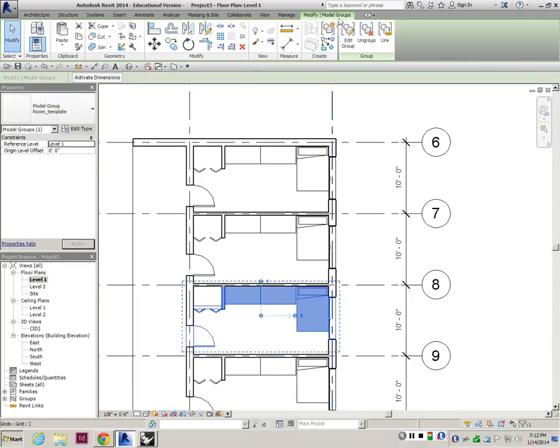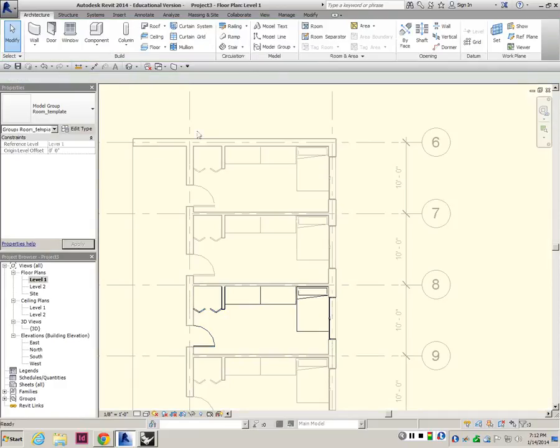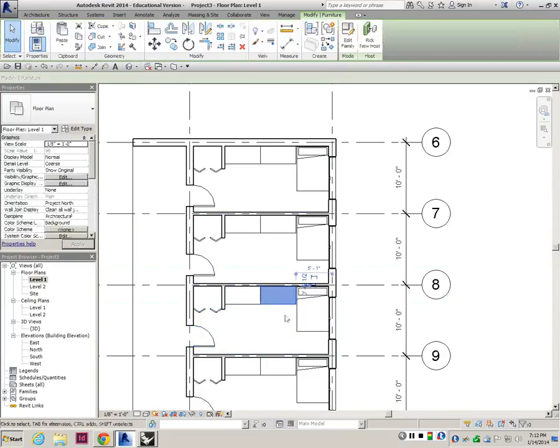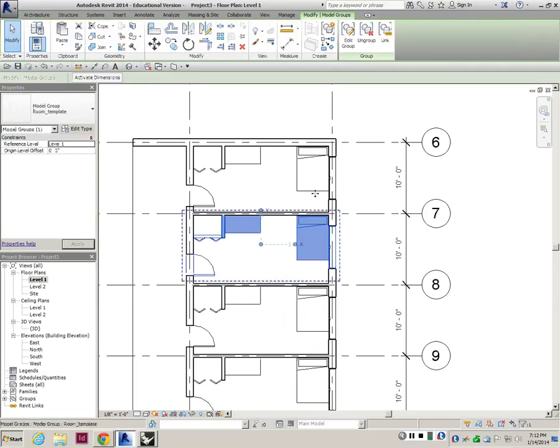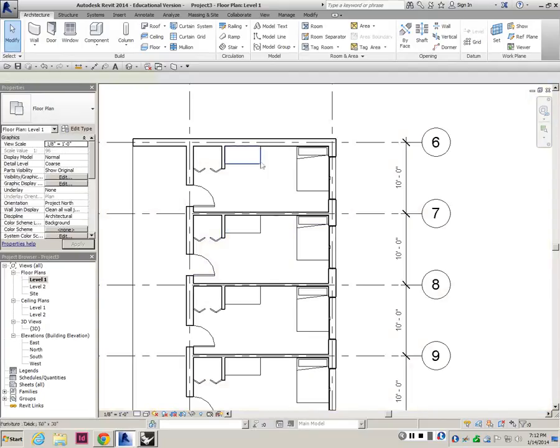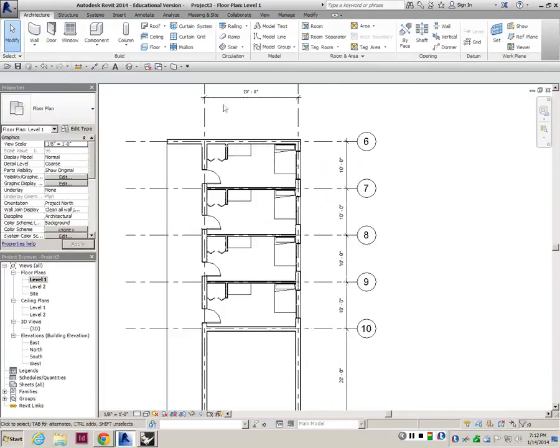Once you select one, under Modify Ribbon tab, there's Edit Group, Ungroup, Link. So you could do Edit Group, Remove, select this guy. Now it's gone. Finish. Let me see again. Now it's taken out of the group, but it's not removed. Let me see. Edit group, remove multiple, finish, attach, done. Yeah, try to do this, and I'll see if you have any problem.